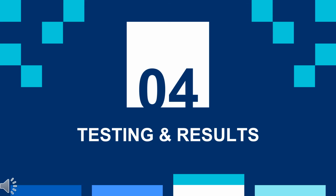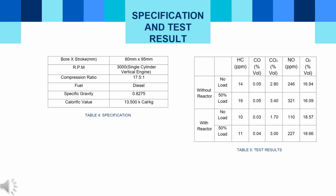Next we are going to discuss the testing and results. In this slide, the specification of the engine and the test results are shown. The engine was started to establish the recommended oil pressure, and it was checked for any fuel, oil and water leakage. After the completion of the warm-up procedure, the engine was run on no load condition, and by adjusting the injection of fuel, the speed was adjusted to 1500 rpm.